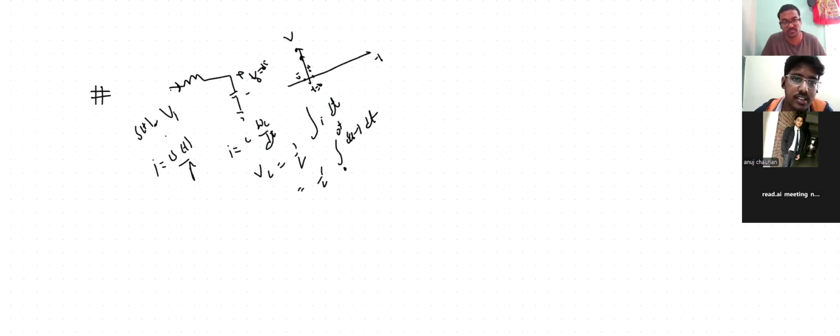And next, after time t is equal to 0 plus, since there is no input, the capacitor should discharge in this path only. Since after time t equal to 0, as I have mentioned, the capacitor has some fixed voltage, so it will discharge. So the capacitor output waveform can be something like this. It is 0, there is a sudden jump, and it will again discharge completely.